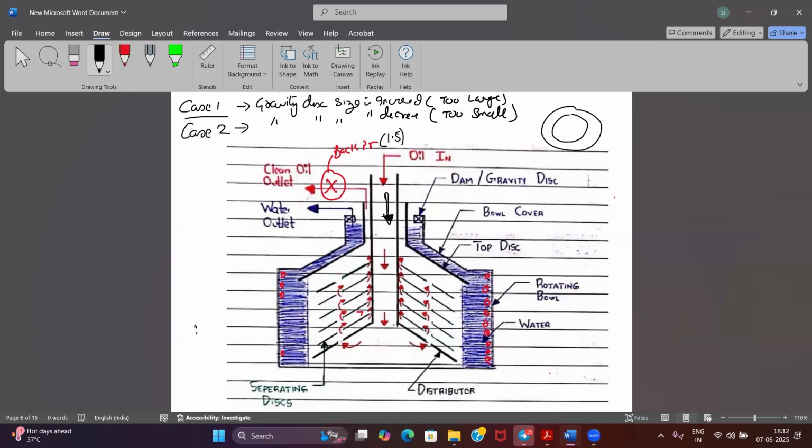There is a bypass valve, and you are adjusting that bypass valve to change the feed inlet. Has anyone seen a fourth engineer doing bypass valve adjustment? He is adjusting the feed actually. So how much fuel oil I am putting inside my purifier